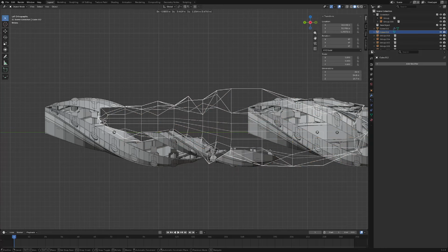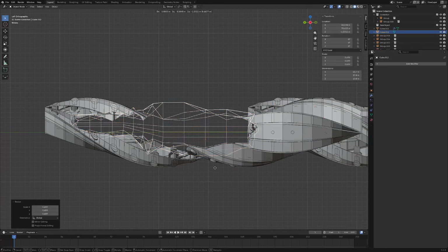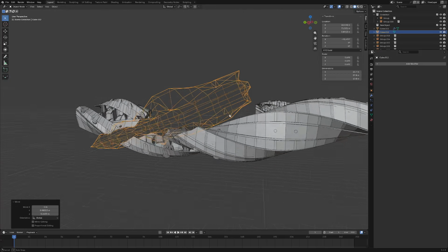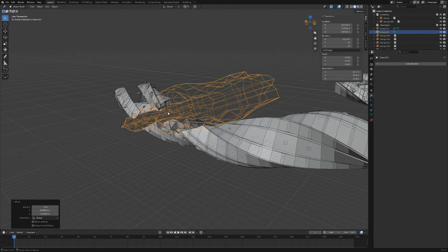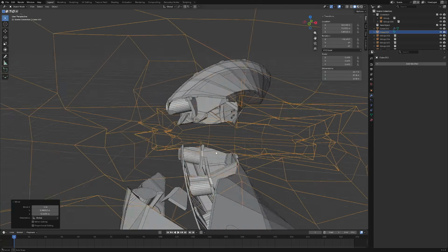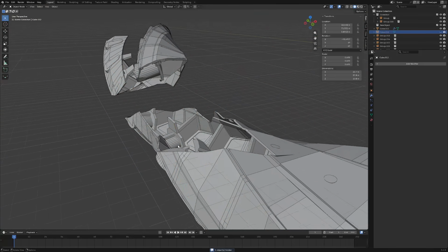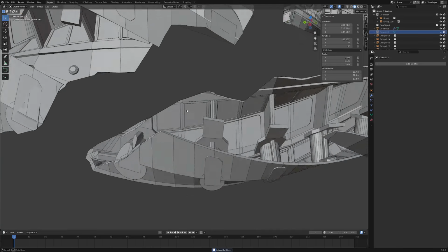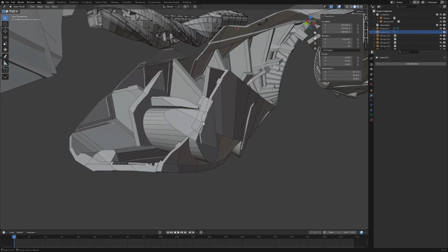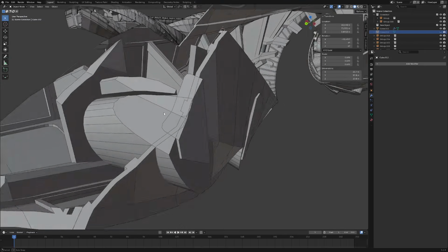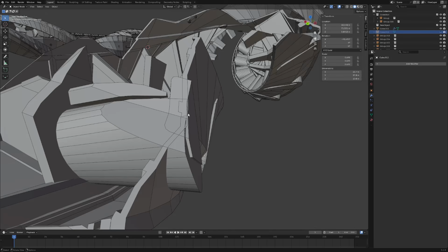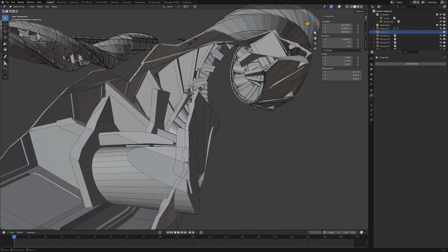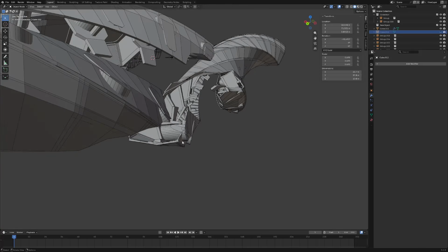So yeah, I think you get the idea here at this point. You could totally make something that looked like it just slammed into this and cut a hole through it or something, right? Not really a big deal. Let's hide that because it's confusing to look at. Let's get rid of this grid floor too, because it just complicates it a bit. But yeah, now we can see what's going on here. This will still require cleanup possibly. Unfortunately, that's the way it is. Otherwise, you'll get Z fighting and other stuff going on with it.